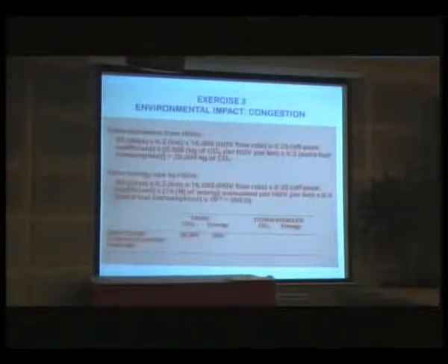The bridge has a life of 120 years, and so in order to reach that life of 120 years, there will be 23 times the bridge will need to be inspected, and we further assume that it's a 4-span bridge, and so we're going to need 4 days to inspect that structure. So the 23 times 4 gives us the 92 days.